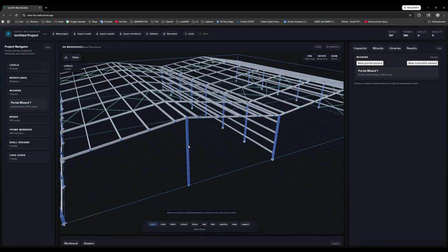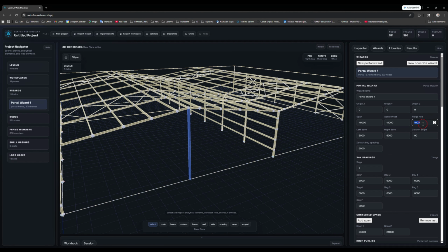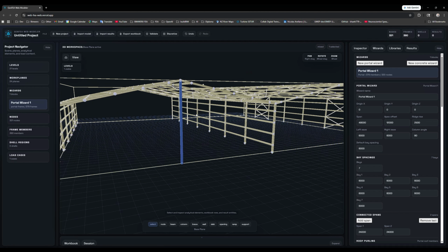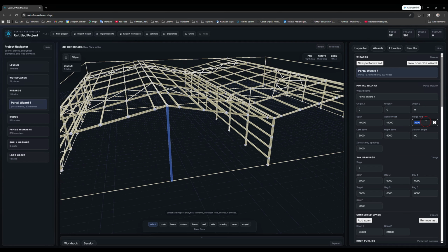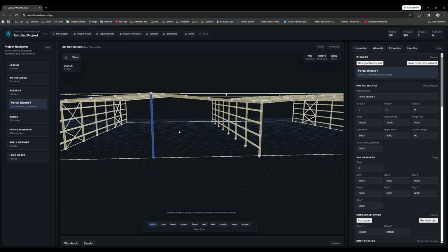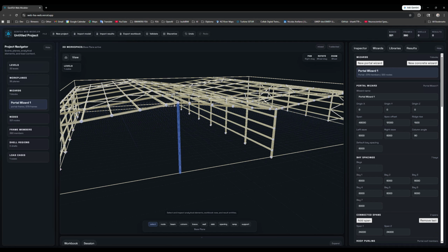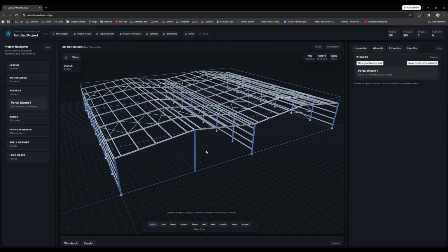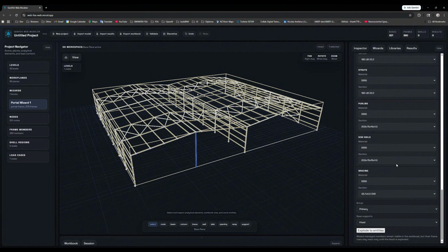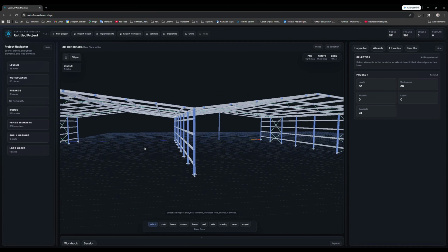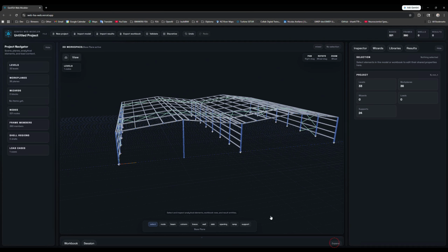If we did that, it's obviously sitting outside of that block. But notice what happens when we adjust the apex height there. You'll see that that column is, although it's been added afterwards as an add-on to that structure, still connected to it in a smart way. So, it keeps that parametric connectivity, and at any point if we want to explode that parametric wizard block, we can do that.